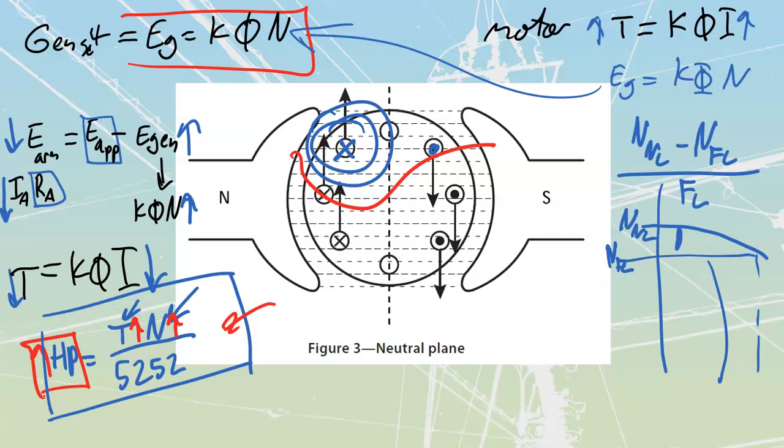All right, so the current that I'm going to have inside of my motor is a function of the counter EMF that is developed by the armature. Whatever I get inside of here, the amount of current in that armature is going to be based upon what I have for my counter EMF over here.